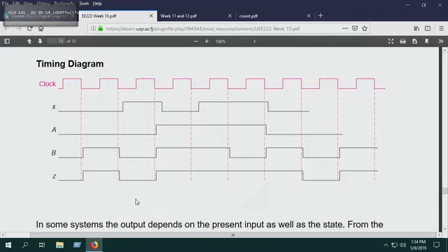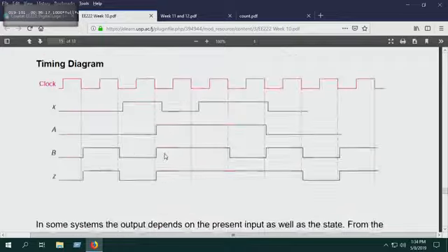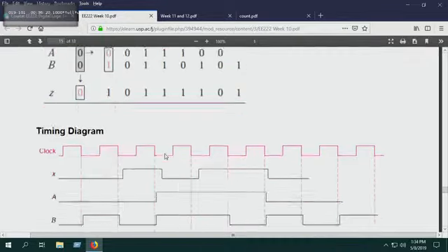Status of flip-flop B is 1. Status of output Z is 1. And then based on the new calculations, what happens? All we are doing is redrawing, in more of a timeline type of situation, what our particular inputs and outputs are. And of course, you can't draw this without drawing the state table. This is more like the state table.